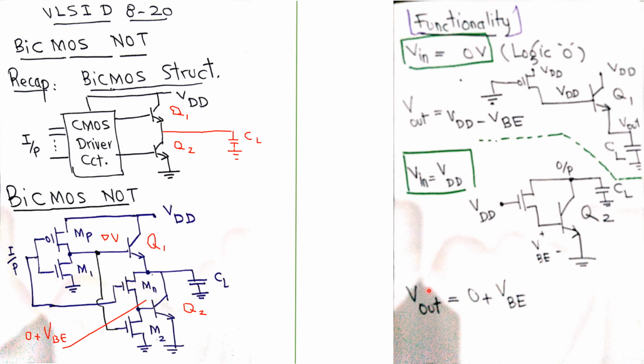So these two are disadvantages, but we have to live with them because it gives better performance. As we studied in the last lecture, it gives better performance for circuits where we have values of CL that are very large. So for very large values of CL, BiCMOS circuits are feasible because they offer lesser delays. In our upcoming lectures, we'll keep on studying BiCMOS circuits. Thank you.